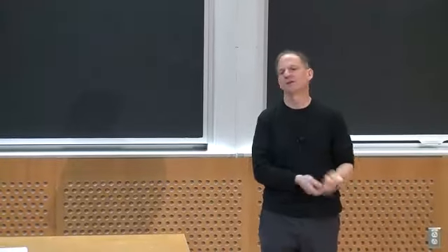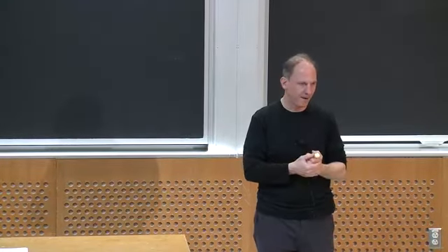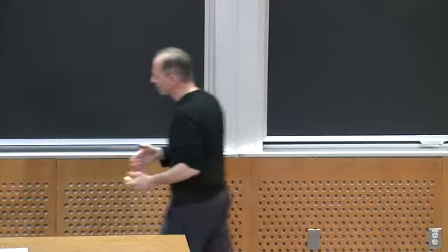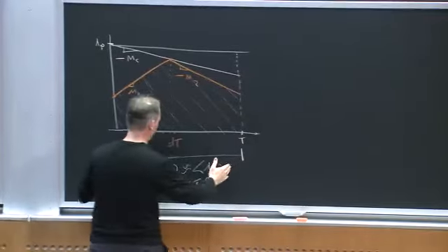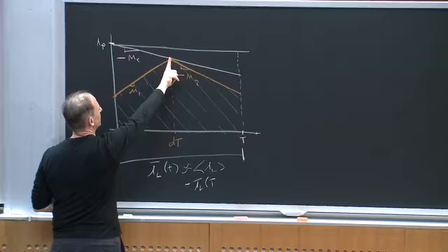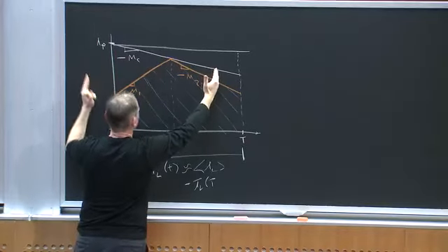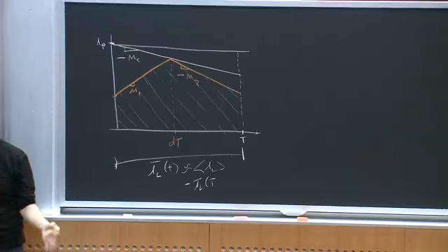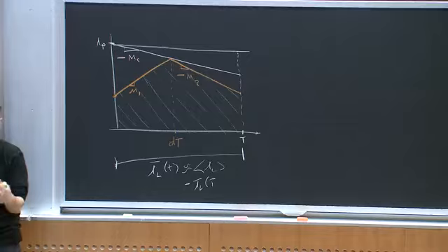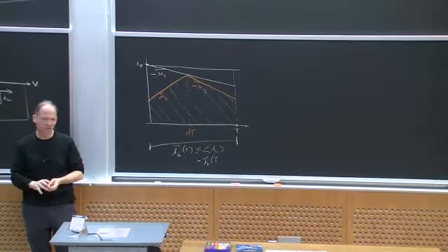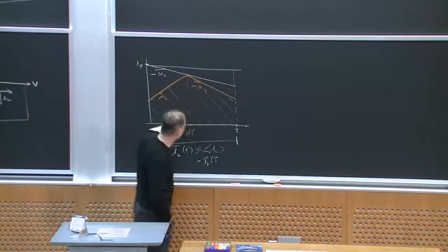All right? Now, if I wanted to be really theoretically pure about this, instead of looking over this window, which is centered at 0.5T, I might look at a window centered at dT and look around here, extending into the different switching cycles. But it turns out for practical purposes, for most cases, you more or less get the same thing. So the approximation I'm going to make is good enough given all the other approximations in the system. Okay? So I'm just going to average it over this window.